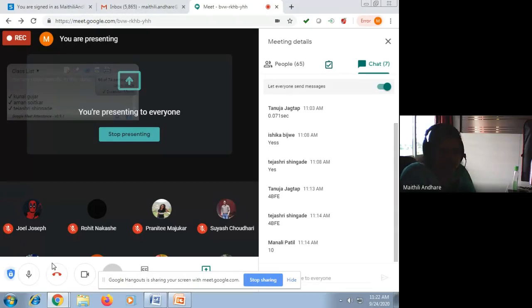Right now we have calculated for 50 millisecond. Load that value in the respective register. Then start the timer. Then poll the TF flag, that is the timer overflow flag. And lastly, stop the timer and clear the timer overflow flag.